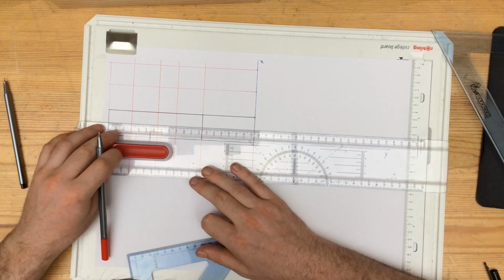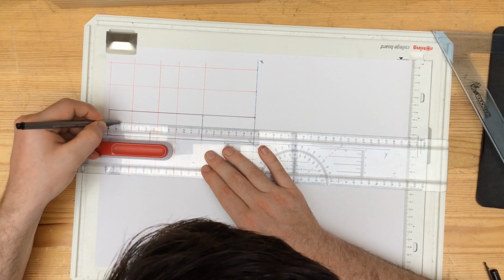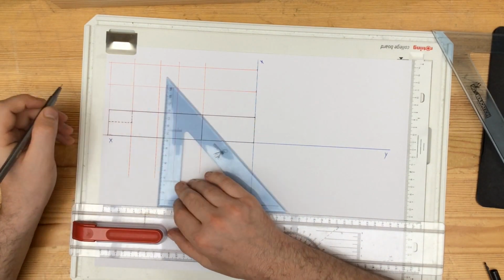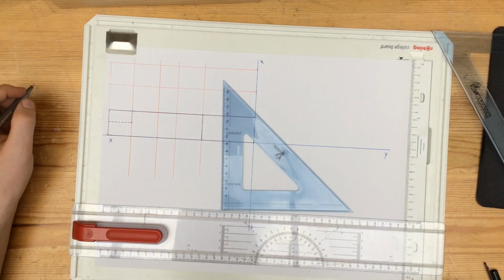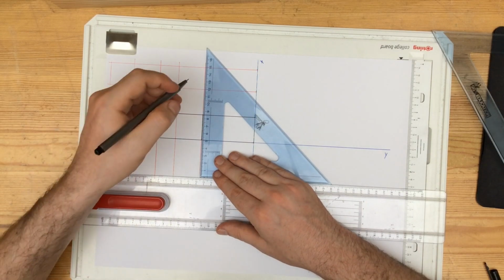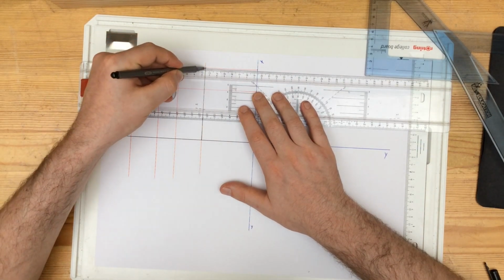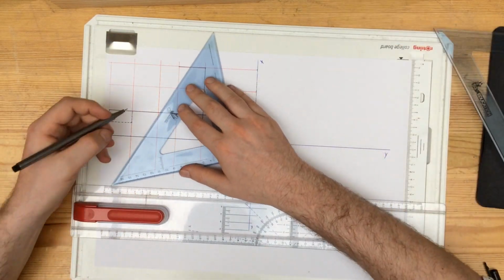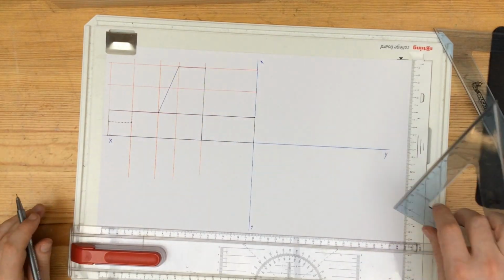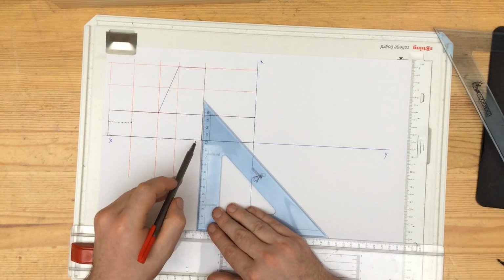I am also going to put in the hidden detail, which shows that there's a notch taken out at the back of the boat, but we cannot see it from this view. We know it exists, therefore we put it in as a broken dash line. The top of the boat can be seen as a cylinder in the 3D representation, but when we are looking directly at it in our elevation, it will appear as a flat surface.